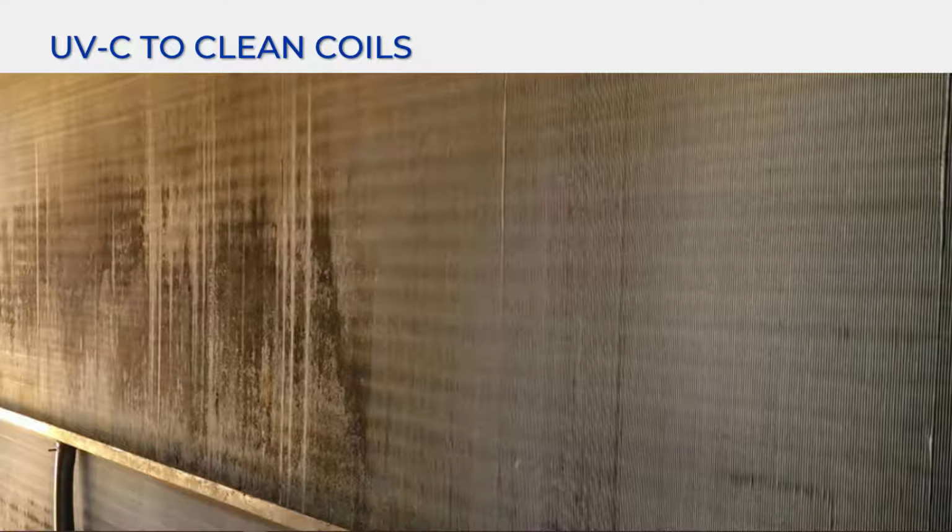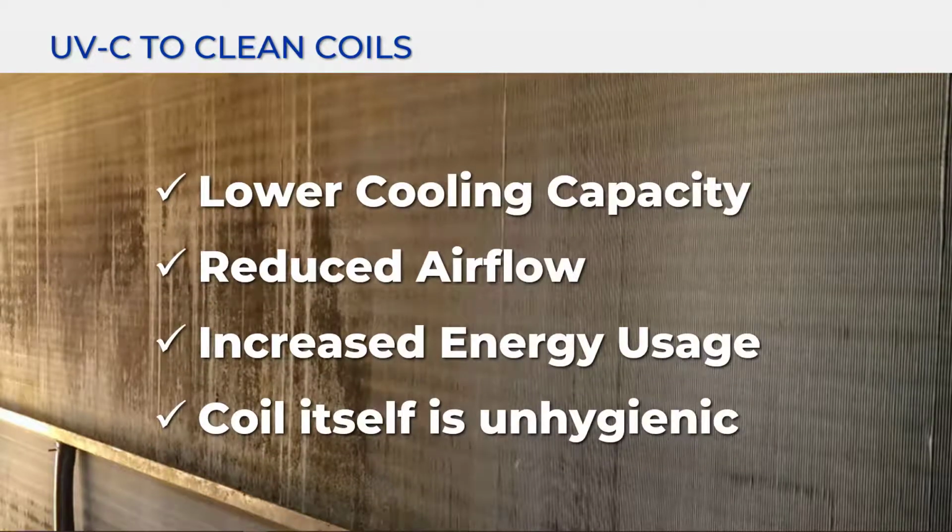Using UV lighting for coil cleaning has been an HVAC industry standard for many years. This technology is what was adapted to our market many years ago and what we have been offering. See, when air condenses on the coil, it gathers whatever contaminants are attached to the water molecules, and if this is left unchecked, it causes the coil to become clogged. This clogged coil hurts the performance of the system and makes the system itself less hygienic.